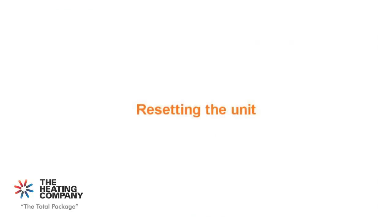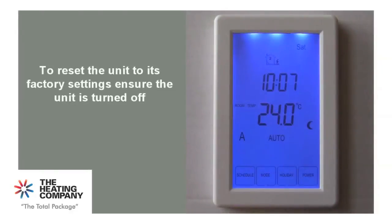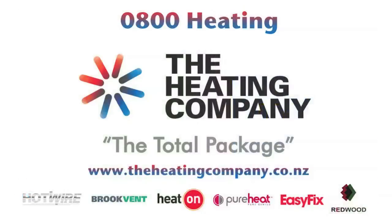Resetting the unit to its factory settings. To reset the unit to its factory settings, turn off the thermostat by pressing the power button. Then press and hold Off in the center of the display for 5 seconds. The unit has now been completely reset.